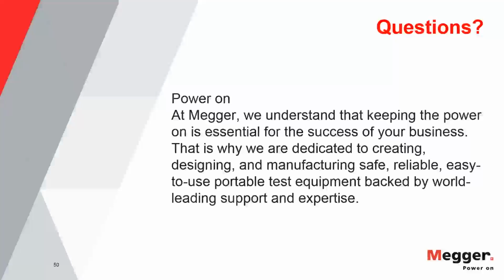To answer that in short, the PD test is the only test in the diagnostics world, so to speak, that can localize defects. And the way this is done is based on TDR technology, or radar, if you want to call it like that. And with that comes all the strengths and all the weaknesses of typical radar technology.